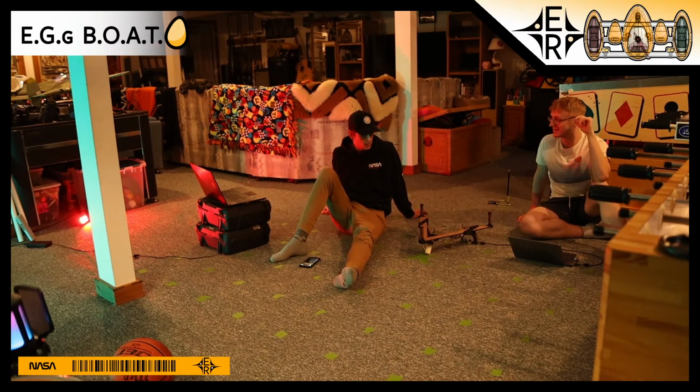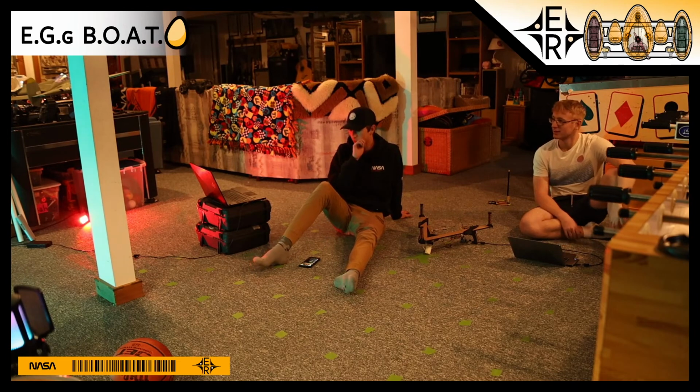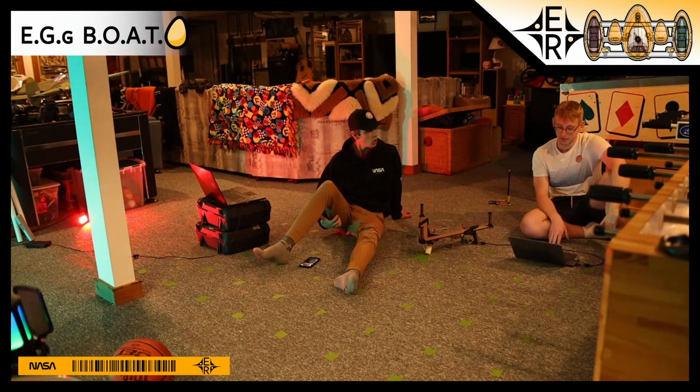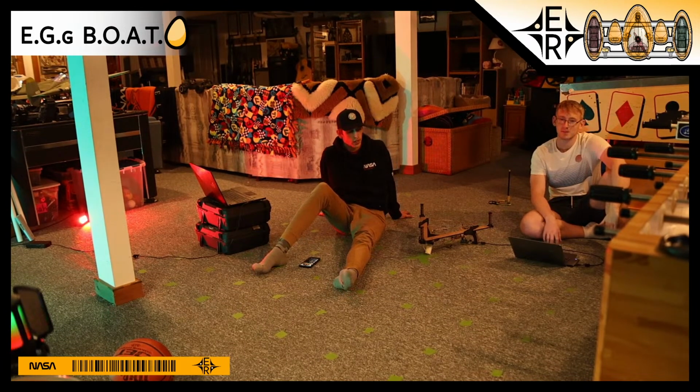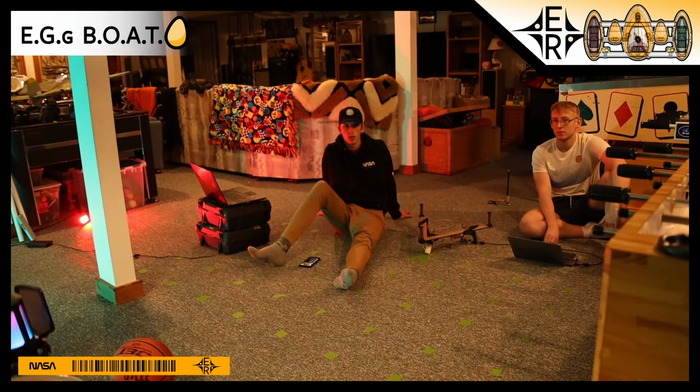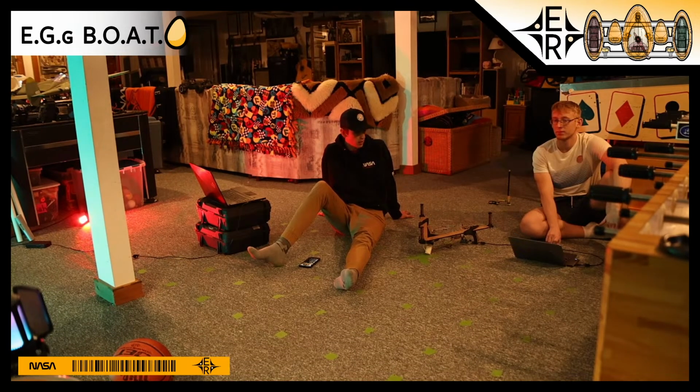Yeah, so prior to this, there was a large period of time, between around mid-March till now, which was a month and a half at least, where we did not have the beacon. And that was definitely when most of the development of this circuit, at least the phase comparison end, was being done. Without the beacon, the only way to test that was to use a function generator as the source of the signal, and then use an oscilloscope to read those voltage values output. So you had to self-manipulate the signal, which meant that we were never really sure how it would act in the real sense outside of theoretical.